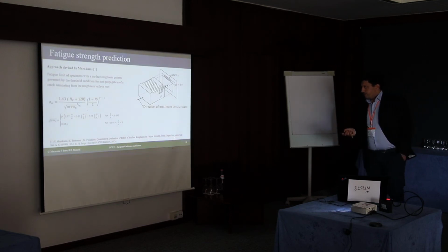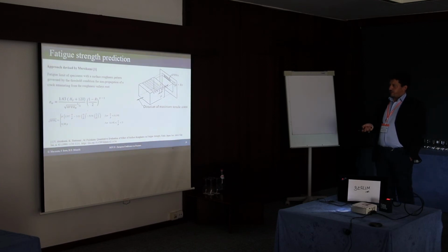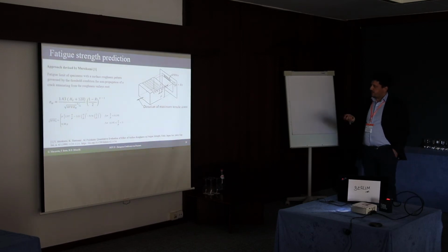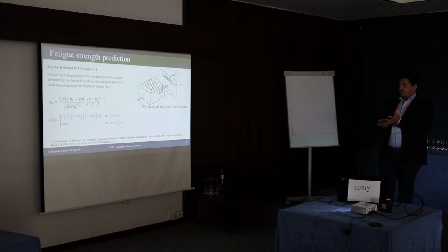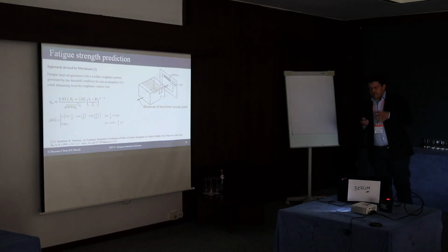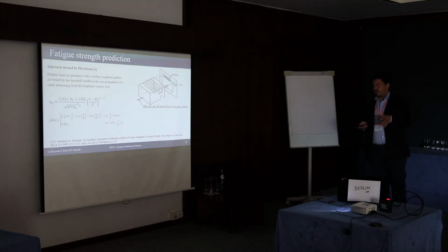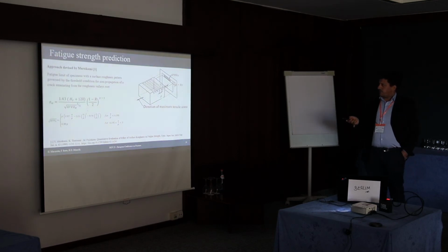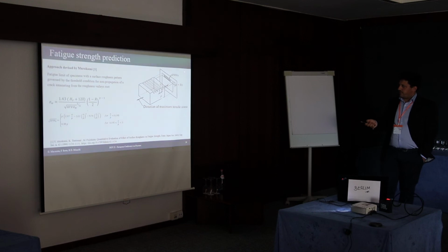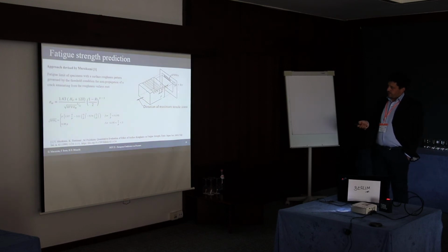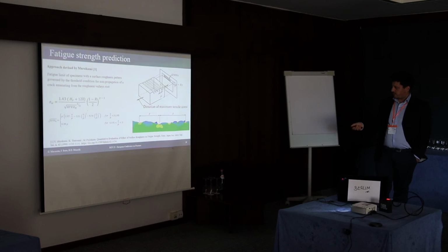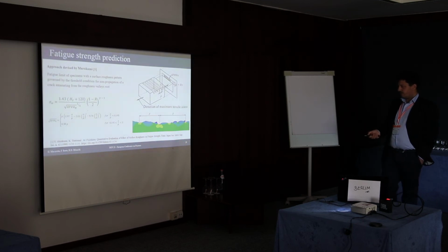So we tried to investigate within the framework developed by Professor Murakami, in particular in view of the presence of non-propagating cracks. What we can say is that the fatigue limit is governed by the threshold condition for non-propagation of cracks emanating from surface valleys. Within this approach, we consider the equivalent area based on the height of the roughness and the pitch between two consecutive roughness valleys. The pitch was evaluated from the finite element simulation, so we consider the pitch only between the steeper valleys, avoiding the smoother ones in the middle.